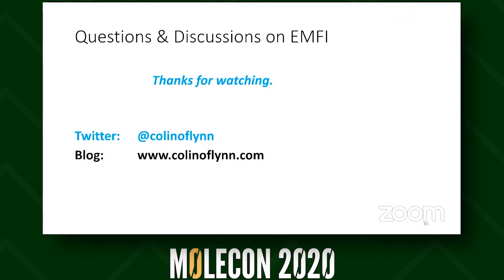Okay, last question is, when would you pick an electromagnetic fault injection attack over a voltage glitch attack? So for EMFI, there's two reasons. Number one can be if you have a case like the Trezor example, where you wanted to do it through the enclosure because it's fundamental to the attack being successful that you don't modify the device. The second reason: for the example of the ECU, it didn't matter. I had to open the ECU anyway. That's not a consideration here.